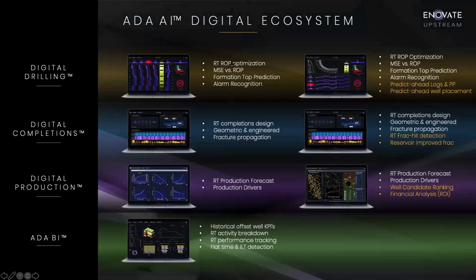And this is important because we not only look at optimizing drilling, but we also look ahead at these drivers from the production analysis that say, hey, we've got to be looking at high permeability strikes. We've got to be looking at high porosity regions along the lateral. And that can only be told if we run production data analysis using flow for offset wells. So once that information is known, we can apply advanced drilling optimization. We call this Drill Plus.